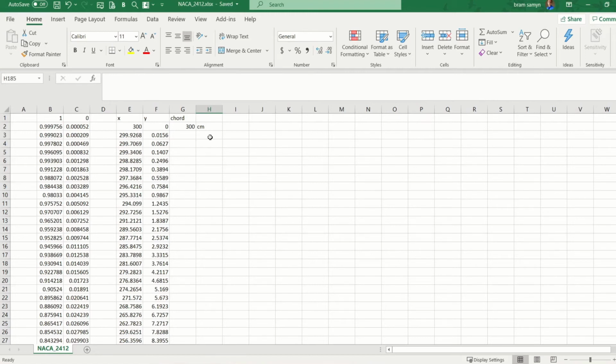Of course, there is a possibility to change the script using something like Visual Code or some other editing software for code or scripts. You can do that, it's perfectly possible, and make some kind of conversion factors so that if you fill it in millimeters, that will first convert it into centimeters so that Fusion 360 can use it. But in this case, let's just use it straight ahead in centimeters. So for this example, it's a chord of 300 centimeters or 3 meters.